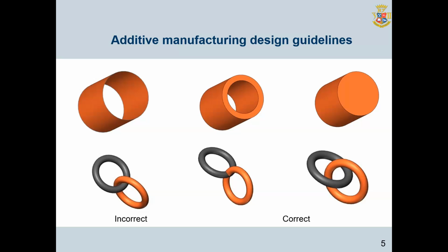Another requirement is the absence of tangent surfaces and faces in the model. Therefore, if the tangent parts make up a single model for printing, it is better to combine them. Otherwise, the mating parts must be separated with the minimum setback provided for each specific material. The last requirement is especially typical for all printed mechanisms and moving parts of models.